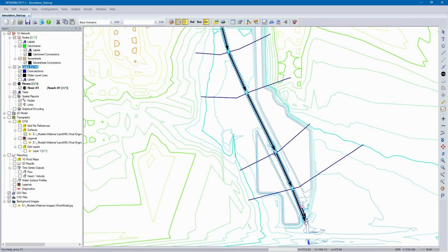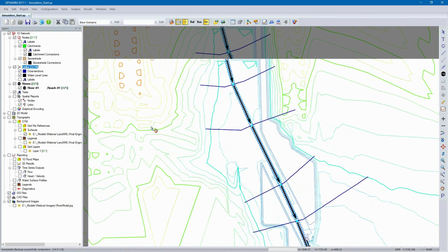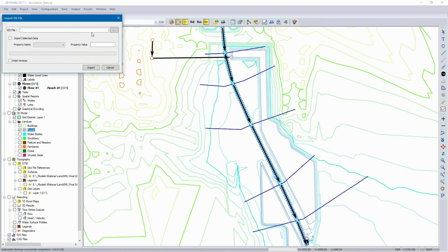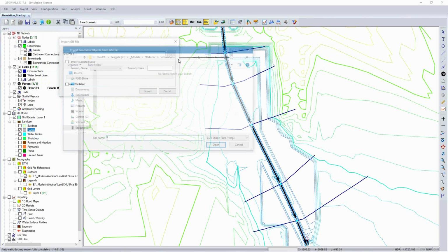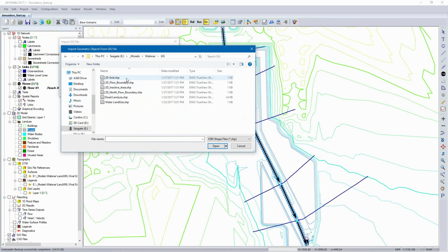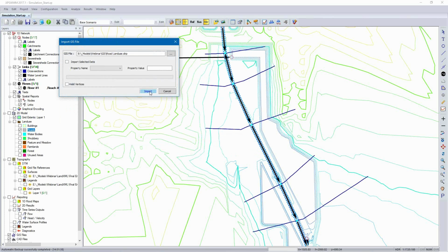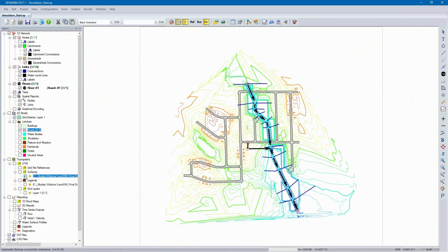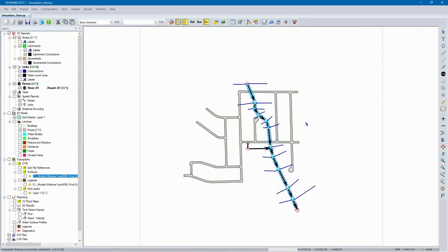There's a lot of hydraulic fun going on in this model, and we don't want to always have to recreate the wheel. We can always look at elements like land use, and I can always bring in GIS data for areas that represent, no, wrong one, for my road, and there's our road polygon.